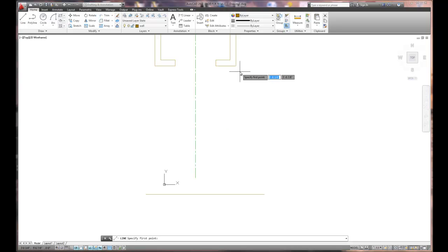There's no left mouse clicks, there's no right mouse clicks. I just highlight. Just come over here, highlight that corner, and you'll notice that I get a dotted line. I haven't picked the thing. This dotted line comes down and anchors itself on the line that I created. Now I left mouse click, and I'm going to go ahead and bring this up 3 feet.